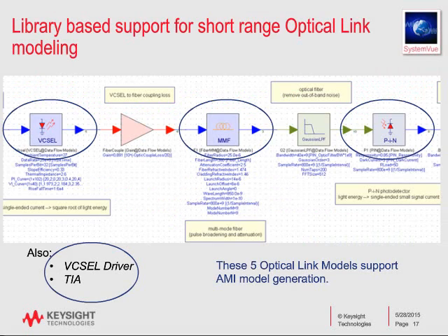Now, to support optical links within that process, we actually have 5 dedicated models that support an optical link type environment. We have a VCSEL driver, the VCSEL itself, which we're going to talk about, multimode fiber, a PIN diode, and a TIA. So those 5 models can be used from System View to build an IBIS-AMI model that you can then use in Channel Simulator.